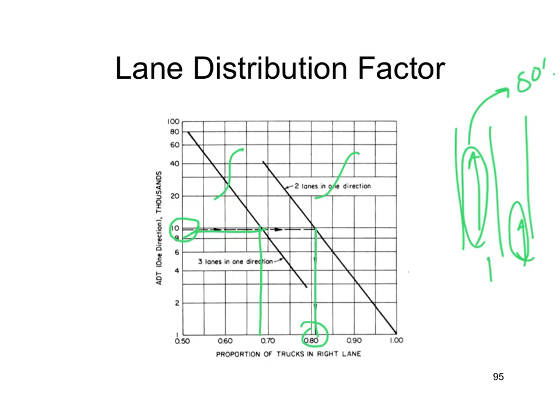For different types of roads and different numbers of lanes, IRC 37 recommends different values of this lane distribution factor. For 2-lane two-way roads, 50% of traffic is taken on the critical lane; for a 4-lane single carriageway road, 40% of the total traffic is taken for the critical lane design.